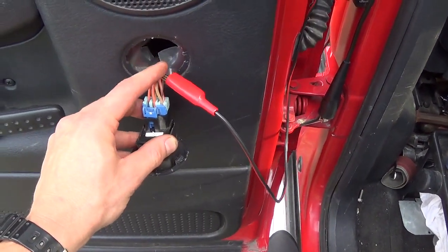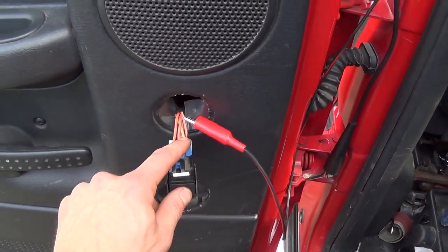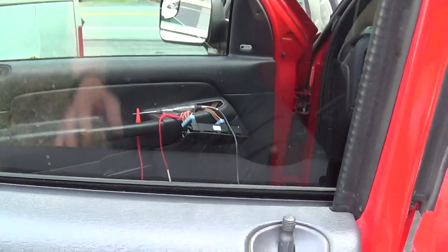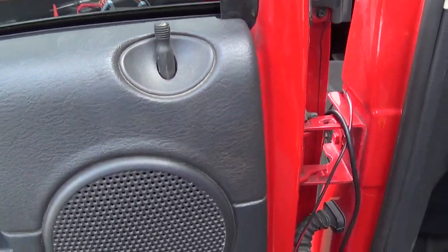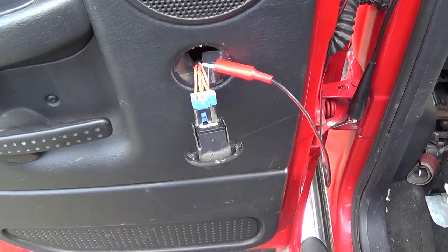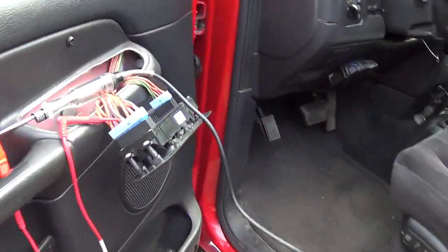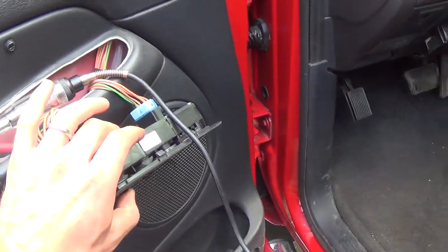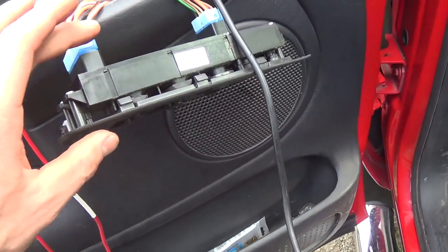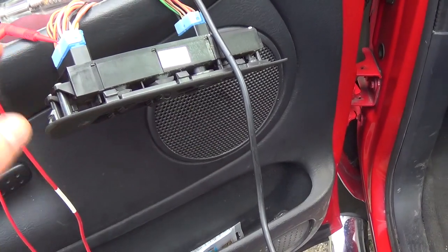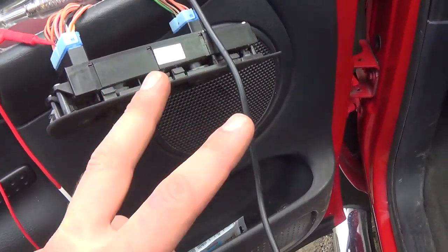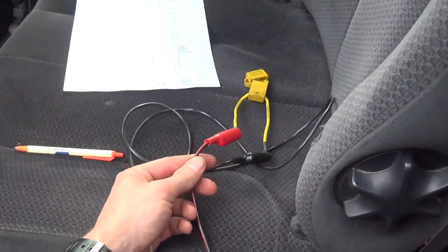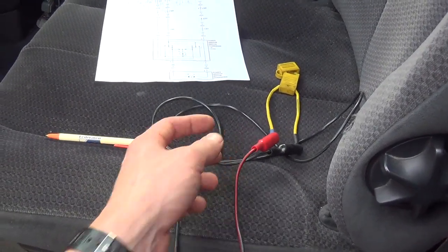So that wire right there is definitely broken between here and the master switch. Confirmed. We bypassed it and now it works. But does it work 100%? Not quite yet. Now we have to figure out, so we can go down but not up. So I think to go up, remember the polarity is reversed on that motor, and right now this is constantly being grounded. So we actually need to send a power.